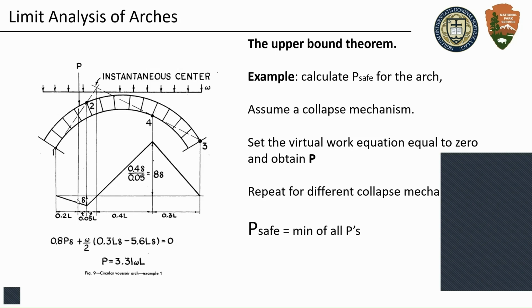And then once we have that deflected shape, we calculate a quantity that we call virtual work, which was proposed centuries ago, and is basically the product of the force times the displacement. And that displacement is when the arch is about to collapse. This is just an exercise that we're doing.